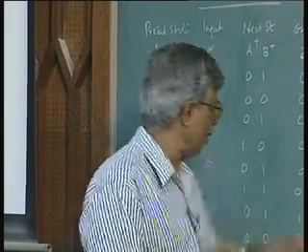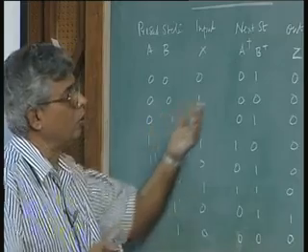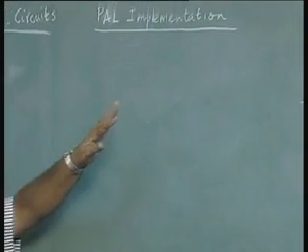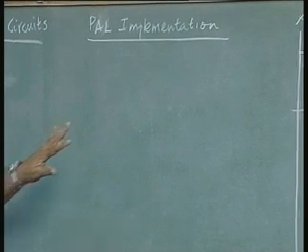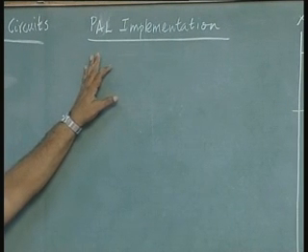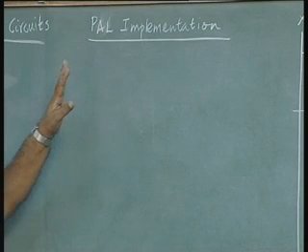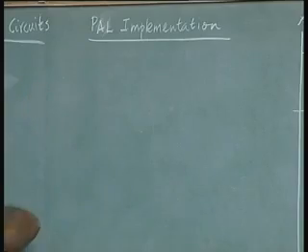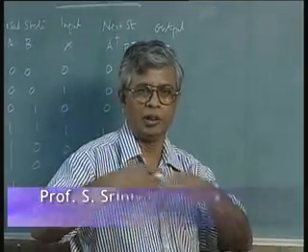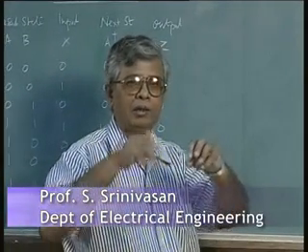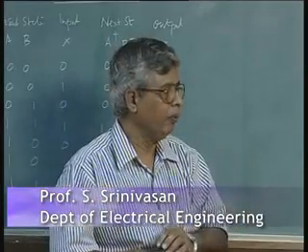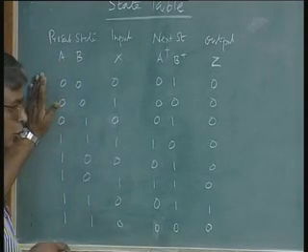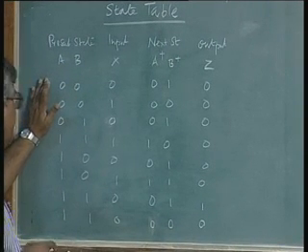So, for that again let us look at this truth table. We will go through the PAL implementation. Again the same state graph I am going to implement using a programmable array logic, which, unlike the earlier multiplexer-based and ROM-based designs that only replaced the combinational logic, is now going to replace the whole thing. There is no separate combinational logic, no sequential logic, nothing. Everything will be put in this one chip when the design is completed. So, for that let us look at this state table one more time. This is the same table we have used again and again.